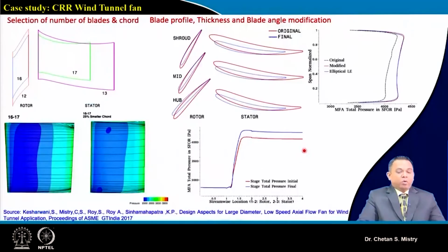So if we go ahead, this is representing this. If you recall, this gives us an idea with fewer blades and more blades for the rotor. We must realize the passage between two blades is the diffusing passage, and it follows what all rules we have discussed in terms of length of the diffusing passage, diffusion angle, inlet area, outlet area.